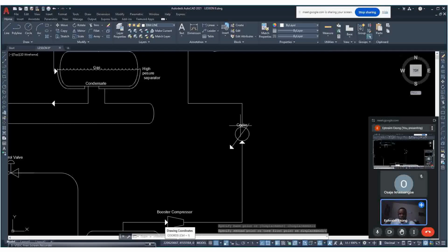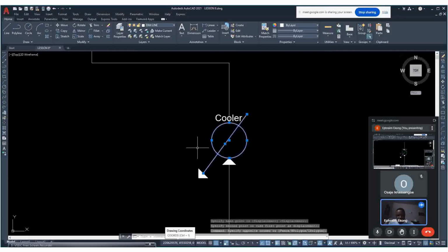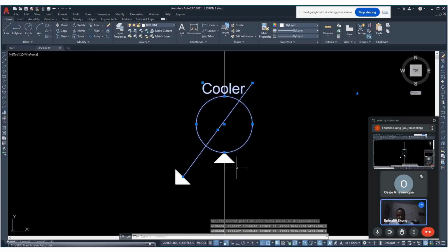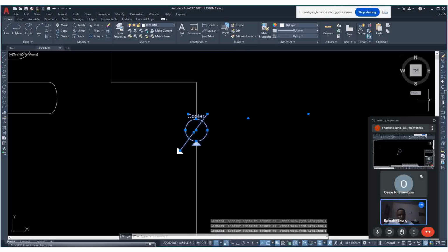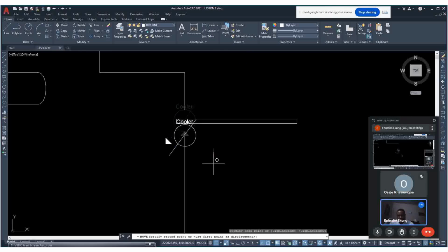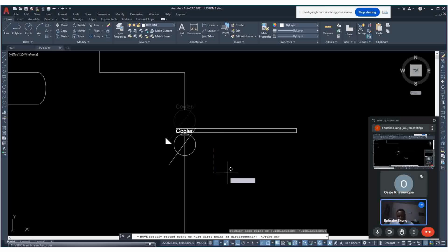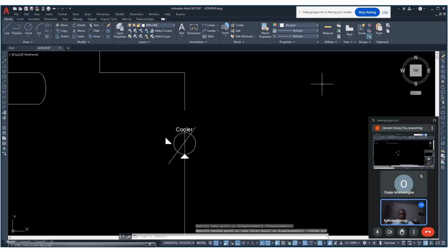This curve part. We can move this one down a little bit, like this, and like this as well. And move it down because of the curve. We need to achieve the curve. Ensure your auto is on because you're moving down straight parts. After that, click on extend, enter, and extend the line.